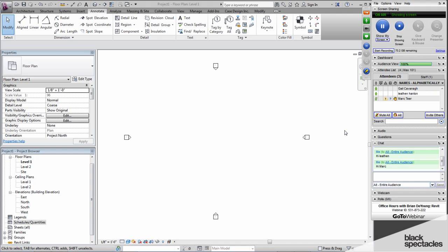So in the lobby, there'll be somebody modeling the interior of the lobby and bathrooms and things like that. So we have an interiors work set and a core work set. For the most part, people stay within one work set when they're working because, like I said, we've tailored the work sets towards what jobs people have on the project.